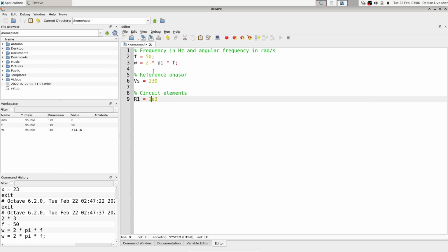So in total it's going to be 1 times 10 to the power of 3, which is 1,000. The reason this is useful, especially when you're entering the values of circuit elements, is that if they're in kilo ohms or microfarads or whatever, it's going to be easier to type the number with a power of 10 after it. Arguably it would be just as easy to type 1,000 here, but it's a good habit to get into to type it in this way, because when you get to very, very small values, such as you'd have for a capacitor, or sometimes very large values, it's going to be easier to manage them when they're written in this concise notation.